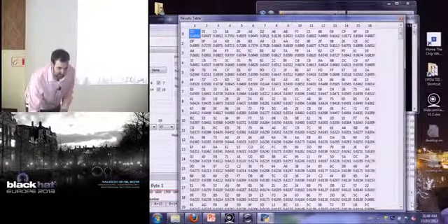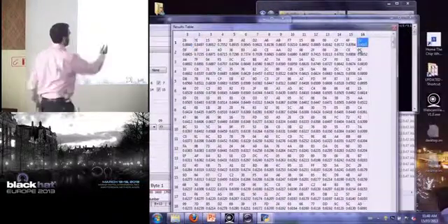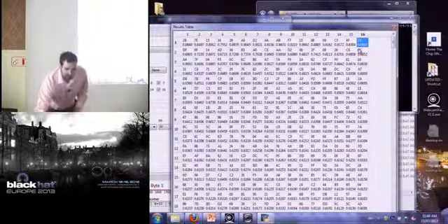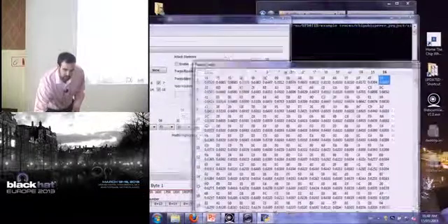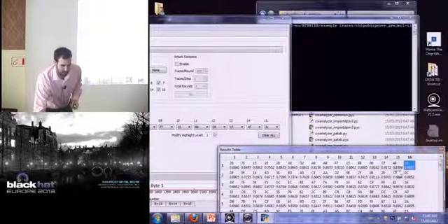We can actually see in the last case, because I cut the trace down too short, this last key byte failed to recover correctly. The correct key is 3C, so it thinks it's 19, which is wrong, but all the rest of them are right. So it thinks it's 4F, which is right, CF, etc.